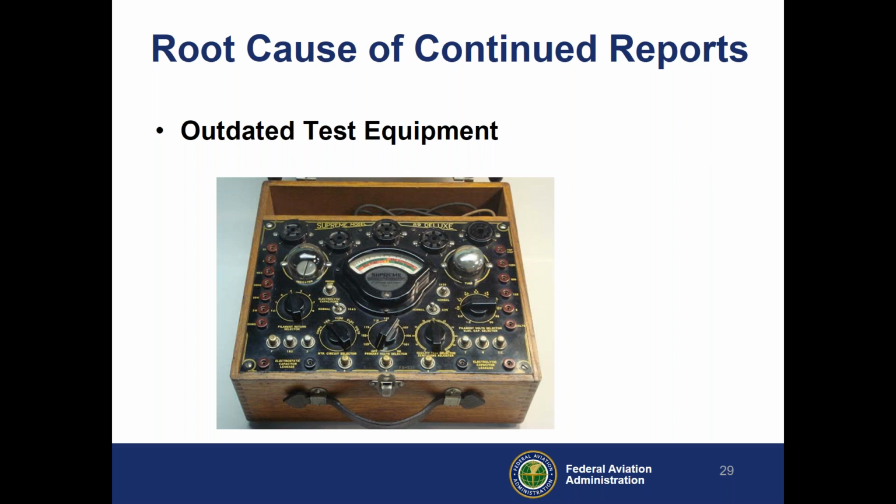That's correct. If the test equipment doesn't have the ability to enter the loss values from the couplers or from cables, then it likely will not work. If it has the ability to enter the loss, then I don't see why it would not. Okay.